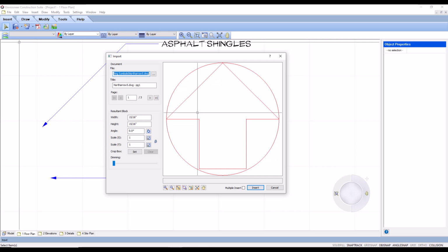Right now it is set to being an arrow that is going to be 15/16 in size. That's going to be pretty small for what I want, so I'm going to use a scale factor of 1/4 inch, and I'm going to go up to 48. And then I'm just going to press Tab. That's going to lock in our value for us, and I can see the actual width and height denoted for me. I can adjust this if I want to.